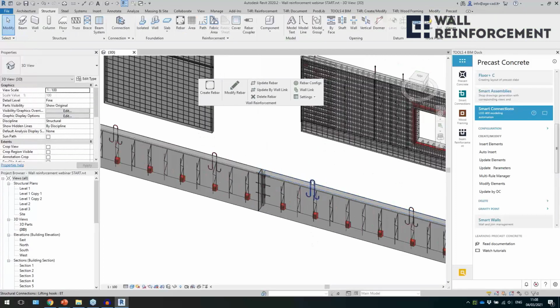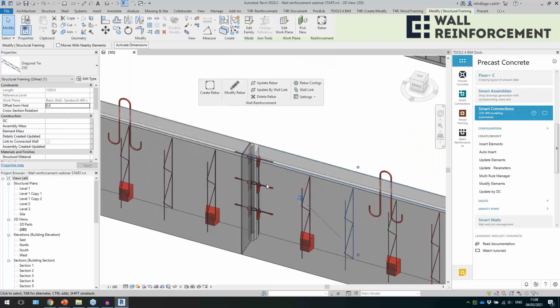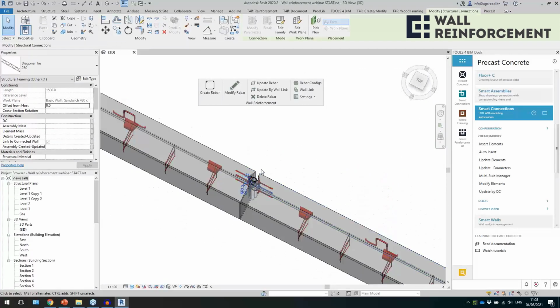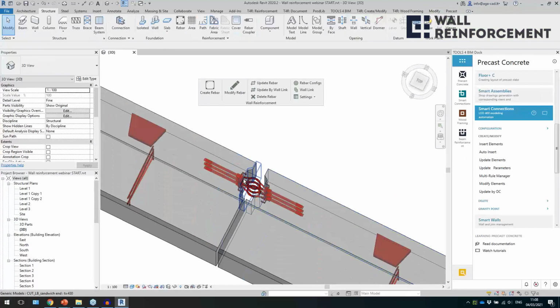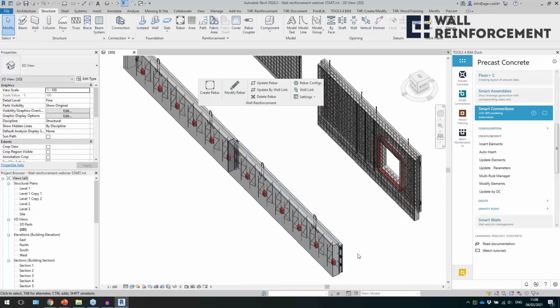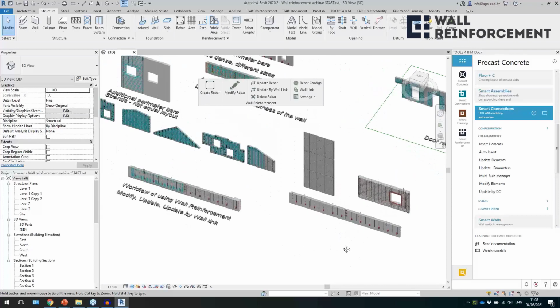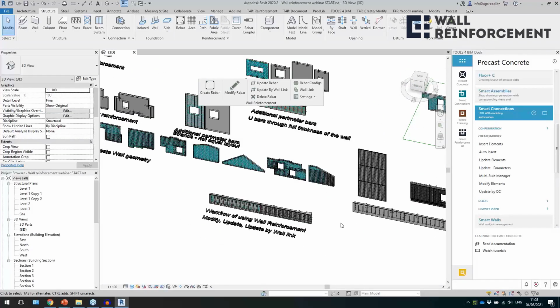So I just placed these by gravity point, these just distributed along the wall. Then I have some cutouts at the end to get this kind of shape of the wall, then place these connection loops and so on. So just to automate this process, but it could be done in both ways. So the wall reinforcement tool works in either way.